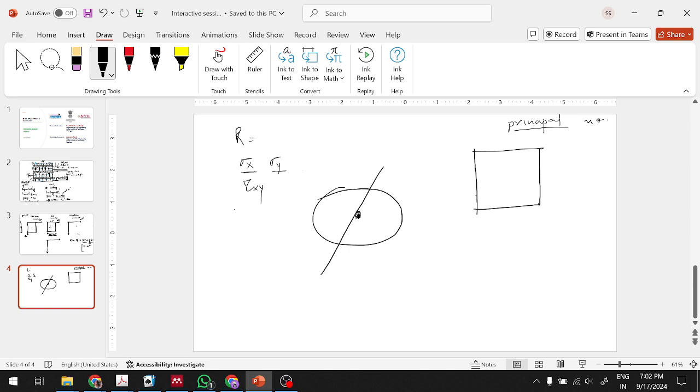Yeah, in that plane. So when I cut through this, it is not necessary that the section I have taken will not have a shear component. But in continuum mechanics, it is always possible to rotate this plane in such a way that there is zero shear stress. Like if we are taking this plane and then we rotate the plane up till a point where we will get shear zero. So we will have those principal sigma 1, sigma 2, sigma 3.